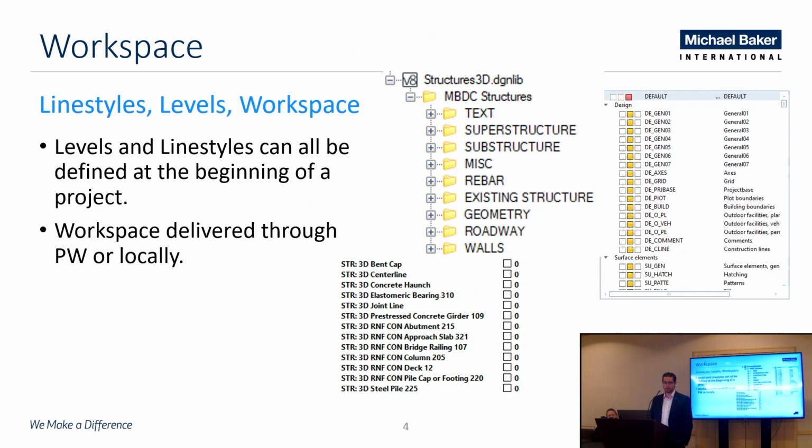So really the first step of any structures project is building out that workspace. Those line styles, those levels, that workspace, so that every time you start a project, you're starting from something standard. So you've got standard templates, pier templates, deck templates, and each DOT is going to be different on this, and they can create that workspace.